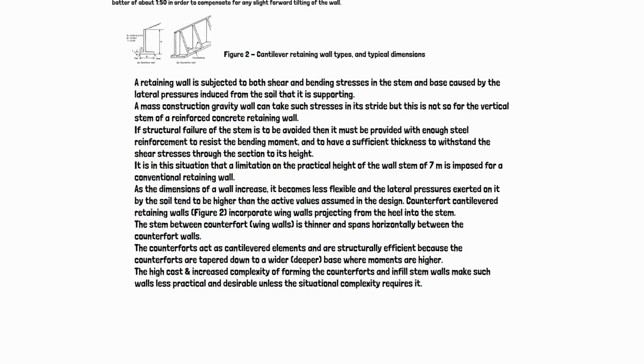However, the high cost and increased complexity of forming the counterfort and infill stem walls make such walls less practical and desirable unless the situational complexity requires it. You can see why counterfort cantilevered retaining walls are not often common, because they have increased complexity, and also there is a high cost, so it is best to avoid them when the situational complexity does not require it.